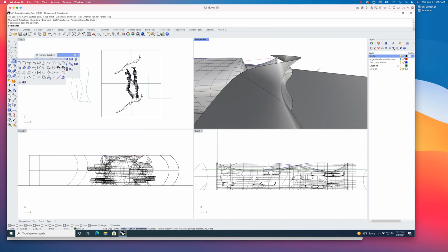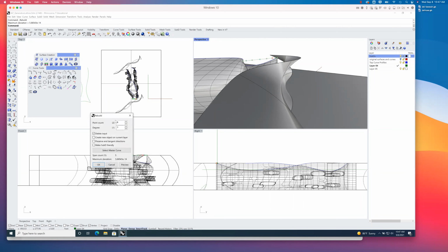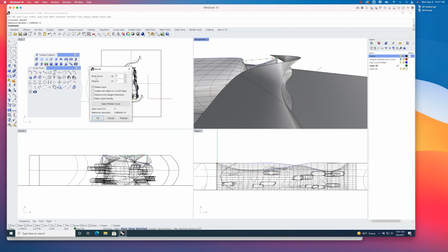Okay. Here's a set of curve tools. Here's the sort of curve modification tools here. Right, I click and hold out. This is fillet one. Right. If I click and hold it out, I can do a number of things. But if you write down one thing for today, it's rebuild curve. Right. I can just type in rebuild. Right. And you can see that there's something that I can do here.